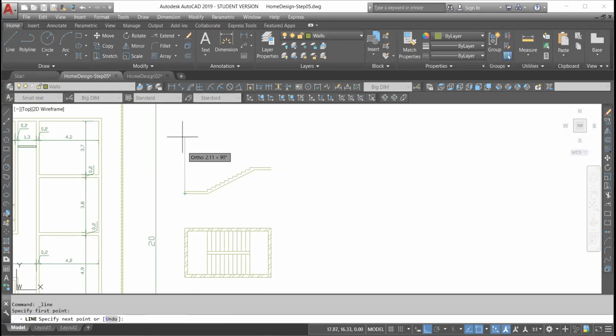From this point, I rise up 3.3, for example, but 3.3 must be from this point here up 3.3 meters. Okay. Another offset. I can use offset 0.2. This is the wall here. The same. If I extend this line, must arrive here. Yes.